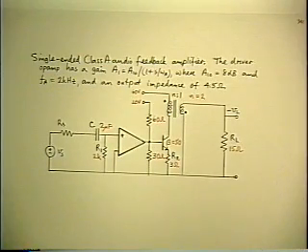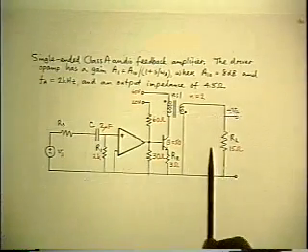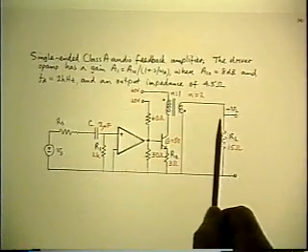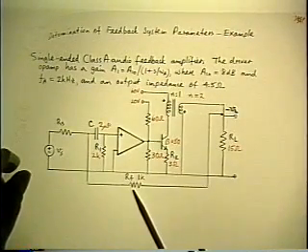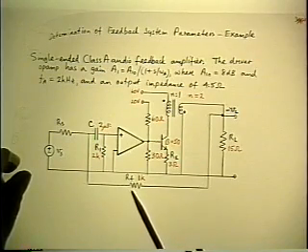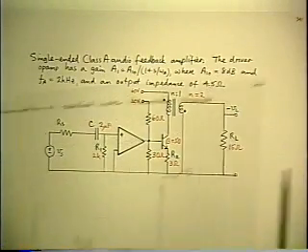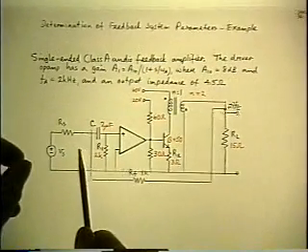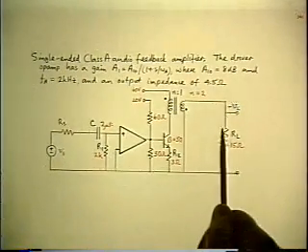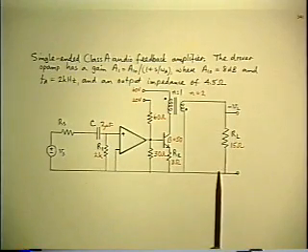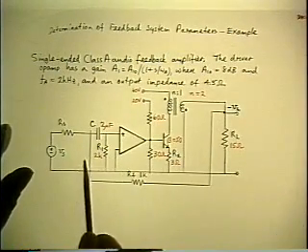The next step of the usual approach is you recognize that you've done that, and so you try to fudge the loading. You try to put another path across here that represents the input impedance to the feedback path. And this is where you start running into trouble. Because obviously you would draw an RF from this point. The trouble is, what do you do with the other end? Because it doesn't go to ground. So it doesn't go to a zero voltage, so it's no good putting RF just in parallel. You've got to do something else with the other end. Well, what? You don't know.